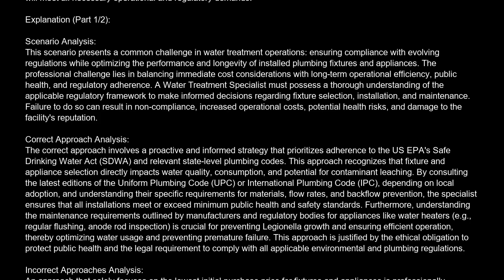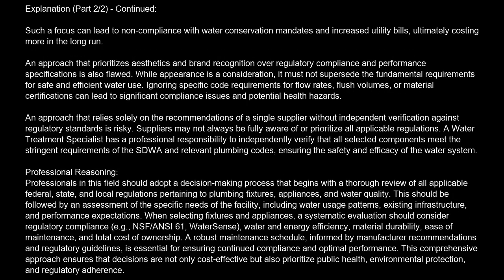Incorrect approach analysis. An approach that solely focuses on the lowest initial purchase price for fixtures and appliances is professionally unacceptable. This overlooks critical factors such as water efficiency ratings, e.g., WaterSense labels, material composition, potential for lead leaching, as addressed by NSF/ANSI 61, and long-term operational costs, energy consumption for water heaters, water usage for toilets and showers. Such a focus can lead to non-compliance with water conservation mandates and increased utility bills, ultimately costing more in the long run. An approach that prioritizes aesthetics and brand recognition over regulatory compliance and performance specifications is also flawed.